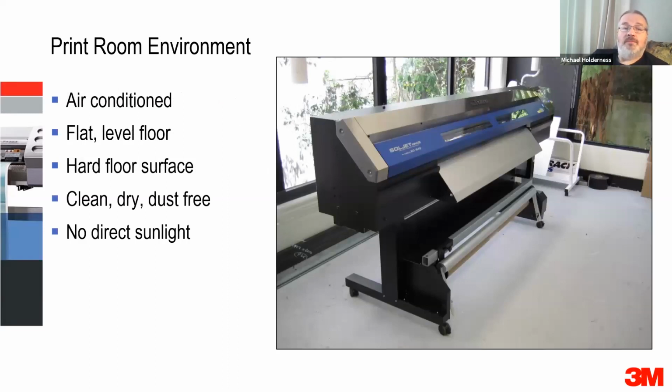The next requirement is for air conditioning. You do need to air condition the room that your printer is in. It needs to be on a flat, level floor. It needs to be on a hard floor. I can't say hands up everyone that's got their printer on carpet, but if you have, you're naughty people, get rid of the carpet as quickly as you can.